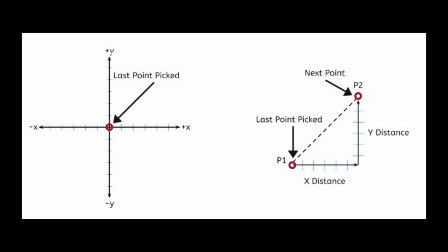Sometimes we don't always know an exact point or our absolute point to where we can just enter 2 coordinates and then go to the next 2 coordinates, etc. Drawing doesn't typically work that way. So we can use another type of point that is called a relative point. Relative coordinates define a location in relation to a previous point. If you look at the example, you'll see if we start in the center of our graph or our coordinate system and start with a point there.